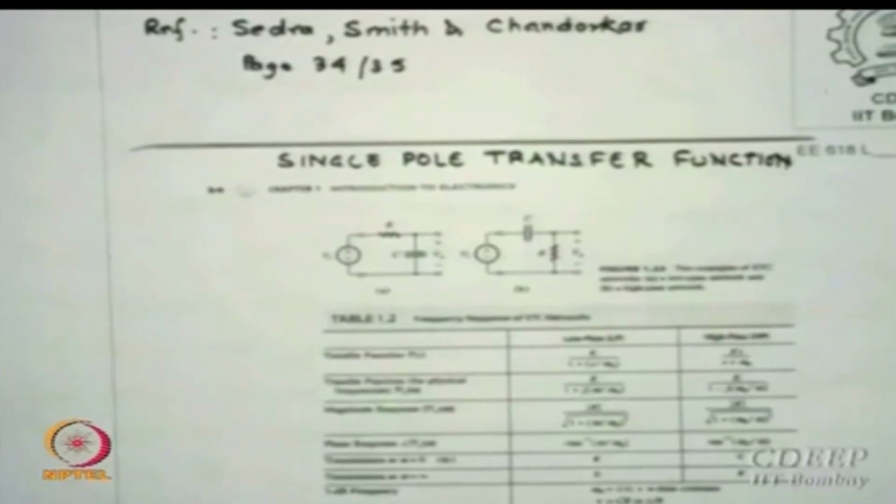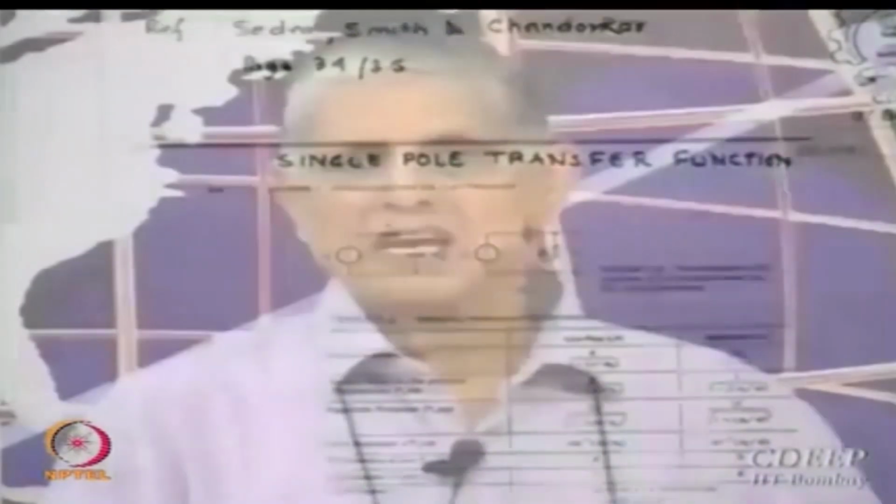the gain is k, the other of course is 0, and the transmission at omega equal to infinity, the low pass gives 0 and the high pass will give k. K is the DC value of that. We also define 3 dB frequencies. Essentially we say at that frequency the gain falls by 3 dB. Okay, that is the frequency we define.